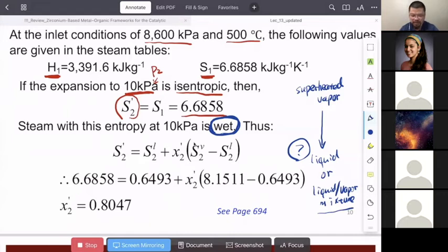So this is why now, if we look at this 10 kPa liquid-vapor mixture, then we don't need the temperature to determine the state, simply because now we have one component, we have two phases, right? So when you use C minus pi plus 2, you receive 1 minus 2 plus 2, which is 1.